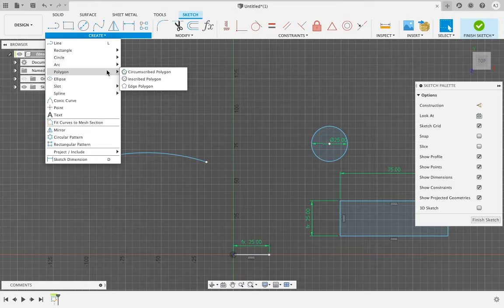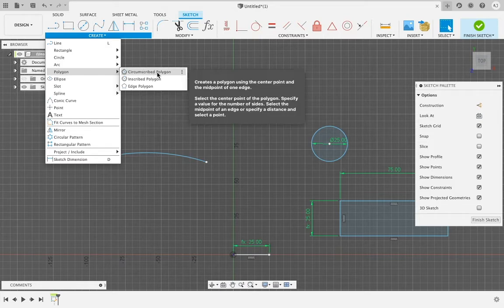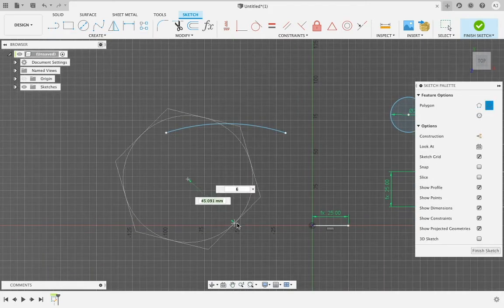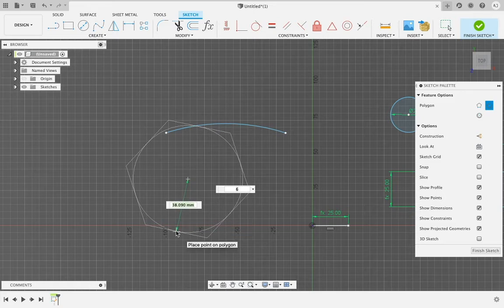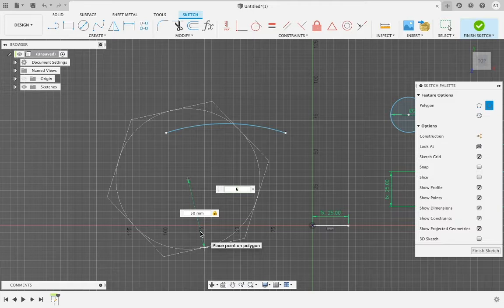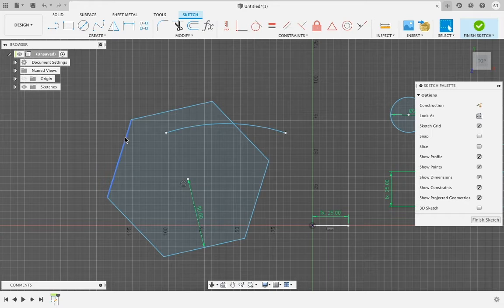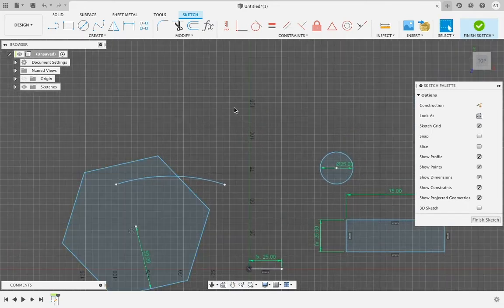Next is our polygons. These are not always useful, but a simple demo is a circumscribed polygon. As you can see, the polygon has the edges on the outside. We can specify an inner radius of maybe 50 millimeters and a face of 8, 12, or 2. Unfortunately, 2 is not available, so you could do 4, you could do 5, or you could do 6, and we'll create, I believe, a pentagon? Yes, I believe, or a hexagon, one of the two.